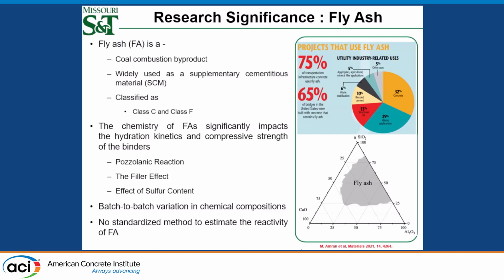Due to the coal source, the combustion technology, cooling techniques, and the catching techniques, there is a batch-to-batch variation in the chemical composition of fly ash. Now, we know that we are using fly ash, but is there a standardized method to estimate the reactivity of fly ashes? For ordinary Portland cement systems, we use the Chapelle, Frattini, and R3 tests, but if we have like 10 to 15 fly ashes, is it viable to do all those tests? So that's why we bring in a concept called